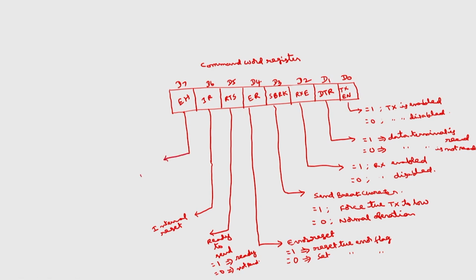This is also an error control signal. So again, the last bit is error control. This is equal to 1 if a sync pulse is detected. So we know that in case of synchronous transmission, we will use sync pulses, whereas in case of asynchronous, we will use start and stop bits. Thank you.